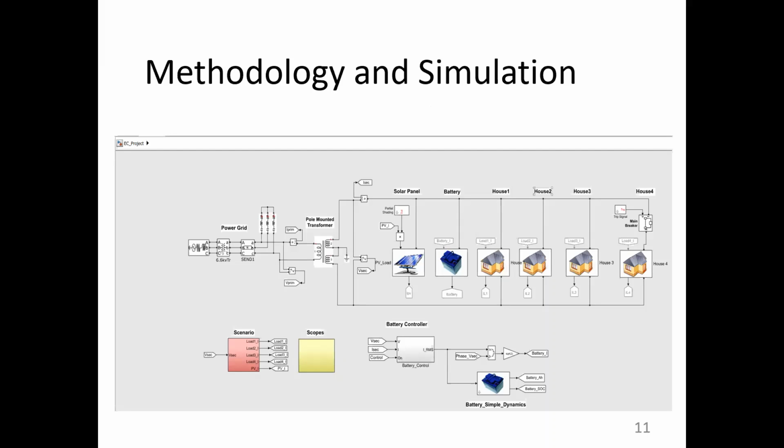So the solar panels are also operating basically within an 11-hour study. And we also took into effect partial shading with clouds and everything. So we also used the microgrid example to help with that as well for a good starting point. We have 32 panels for our solar system to help produce 8 kilowatts for the whole community.